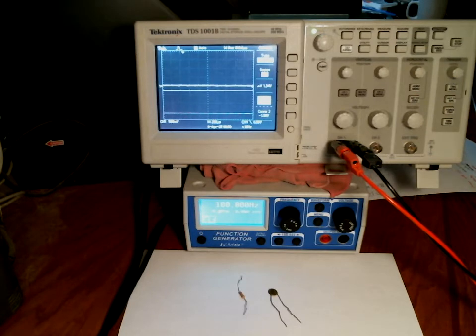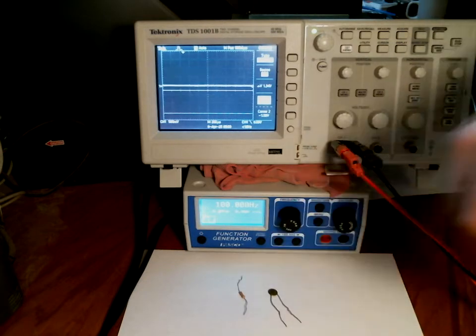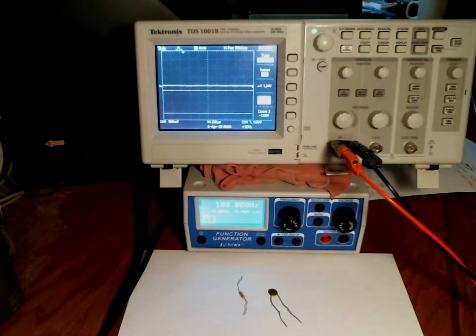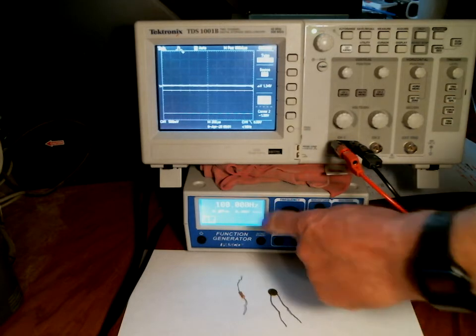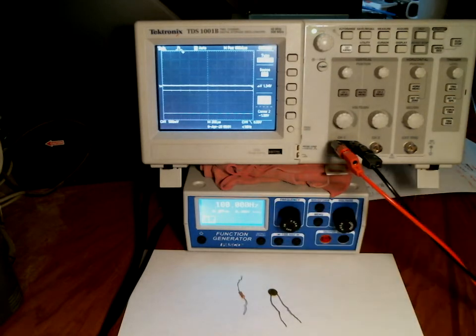We're going to use this square wave generator to drive our series RC circuit. So it's going to just repeatedly kick the capacitor by charging it up, and then the capacitor will discharge itself through the resistor. And it'll do that over and over again. I've put it on 100 hertz right now, and that's chosen so it's considerably longer than the RC time constant. That gives us time to see a lot of the exponential decay until it's pretty much completely decayed.